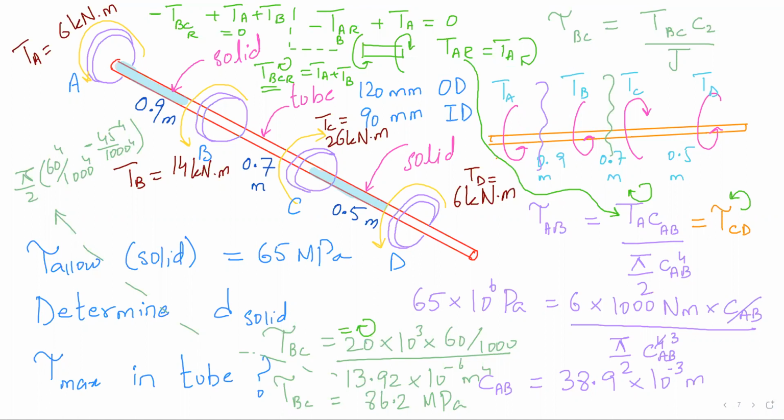There is a tube in the BC part. Shouldn't it affect the first polar moment? Of course. So what you will do is you will have the total twist AD equal to the twisting that happens between AB plus BC plus CD, because the rules of the game that we have set are the same. Whenever you see a change, you incorporate that in your cutting and everything.